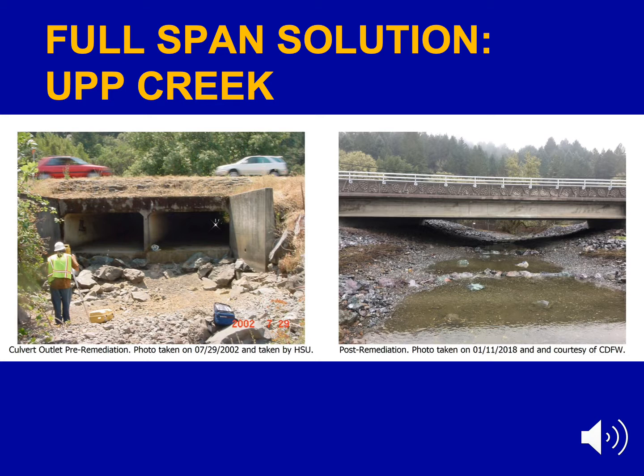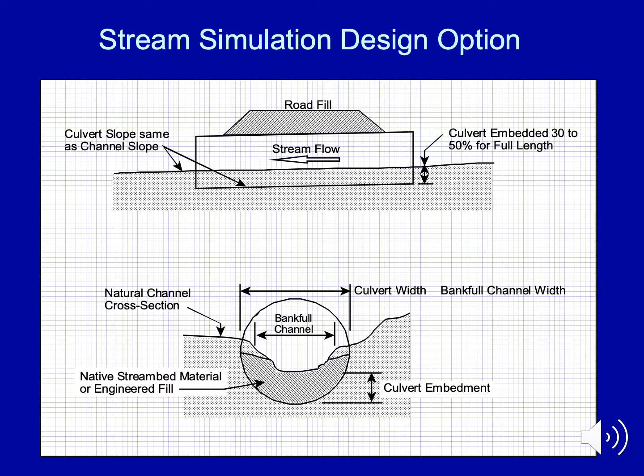You can see abutments out of the bankfull channel. Bankfull channel is roughly right there to there. And right away you can see the heterogeneity of the sediment deposits that are moving through the system. There is a very large, nice cobble bar forming about 2 years downstream of this that I've been told they've seen a lot of successful spawning on, but a lot of that comes from just reestablishing sediment continuity through this crossing. When you have this kind of system, you're not going to get that nice cobble bar developing right downstream. Here you do.